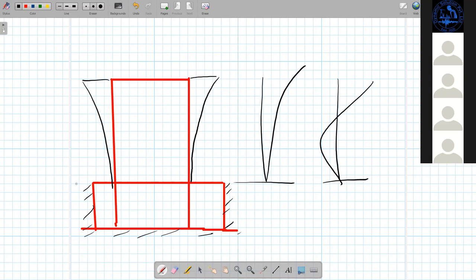So what should you do? First of all, you should consider the number of modes which have 90% of this mass, this W. So 90% of W, which is above that, you should consider. And you should calculate the shear force here. Now the force acting on this portion, if we are going by Indian code, will be Z by 2 into the W of basement.